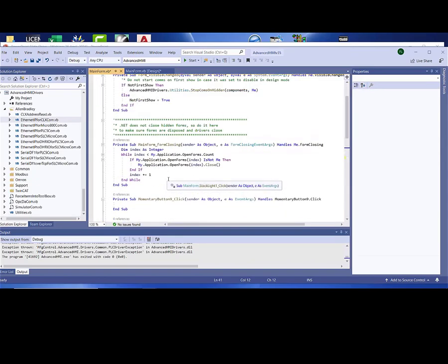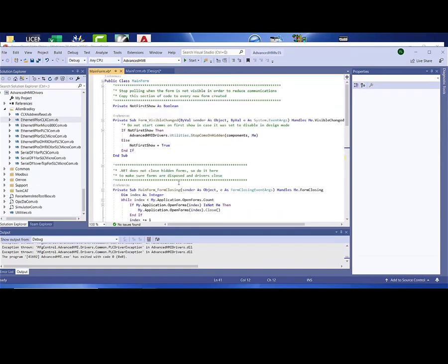You would go to the routine having to do with the driver and type it all in there. So there's HMI drivers. This handles things like when you close the form, shutting down the driver, because if you didn't, you might find that you have 8 copies of the driver running because you've opened 8 different screens that all have to link to the objects on the screen.